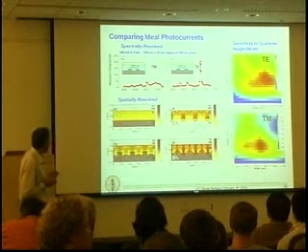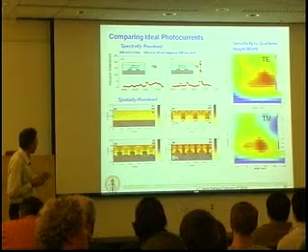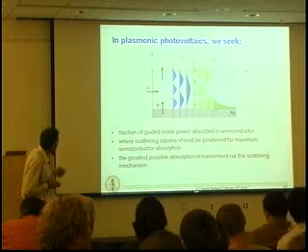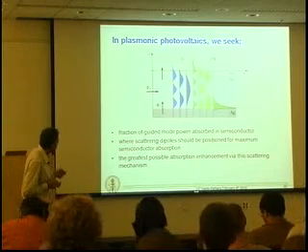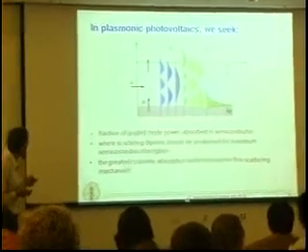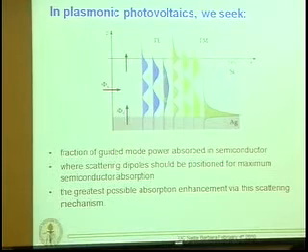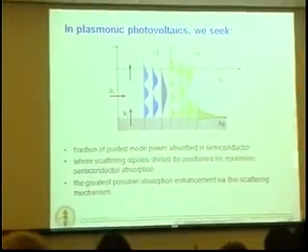These are modes of the periodic structure that exist in this thin film. And these modes that propagate along, this shows the cross-section conceptually of the different mode profiles for the surface plasmon polariton mode, which hugs the interface. Here are TE modes, the lowest order, which is peaked right in the center of the dielectric part of the semiconductor and so forth. And you can see they have different balances of absorption in the metal and the semiconductor.